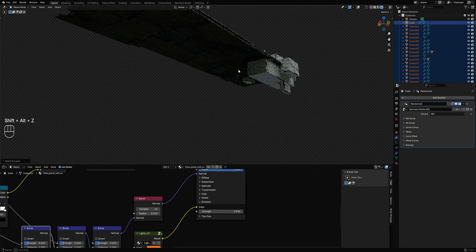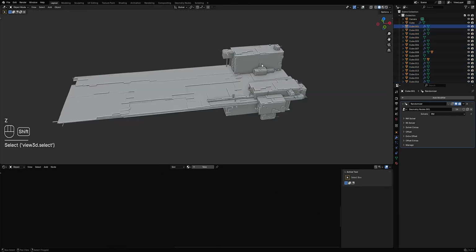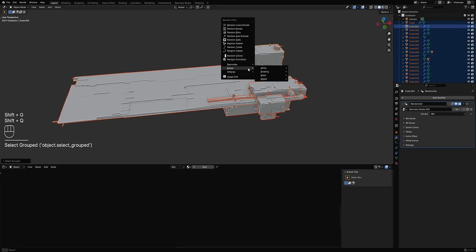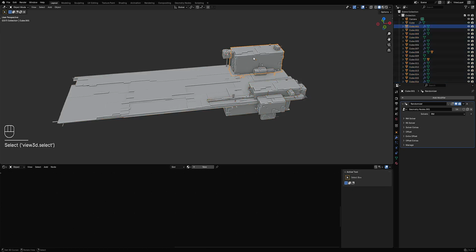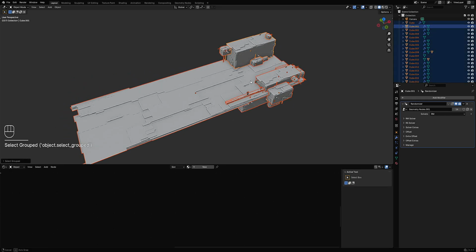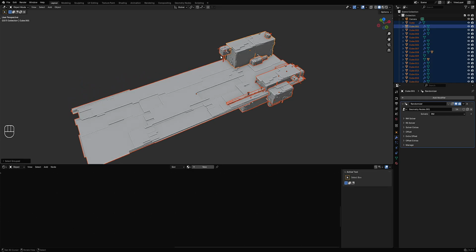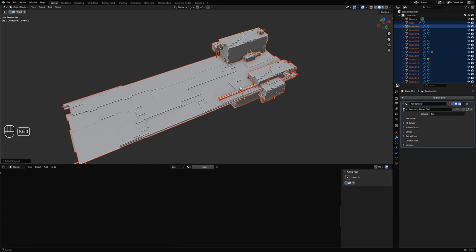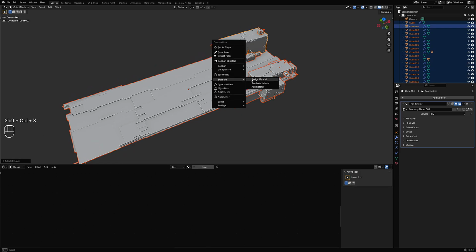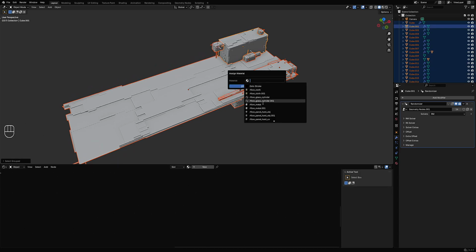Let me see. Okay, so selecting all the mesh. That is Shift G and then T to select all the mesh type. That is based on the selection. If your active selection is a mesh, if you use this Shift G and type, then it will select all the type of objects similar to the active selection. And then materials, assign material. Where is that? Airflow soft UV. Where art thou? There we go. Okay.